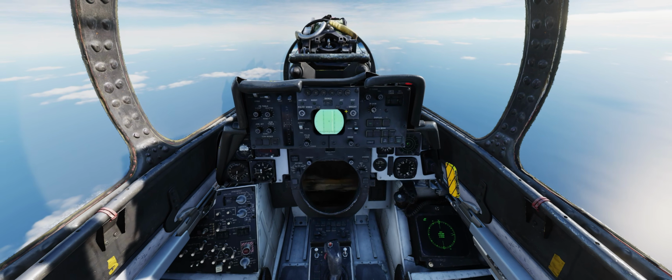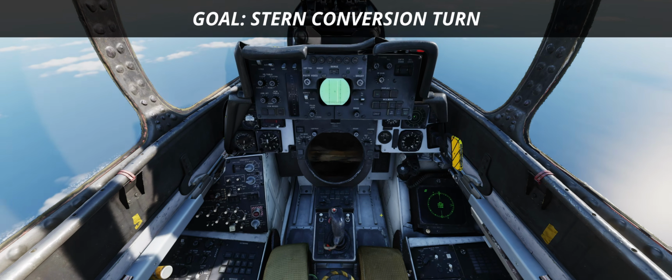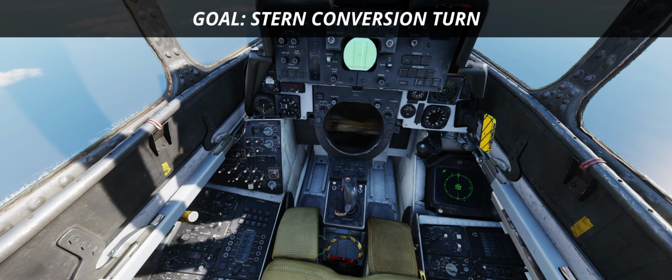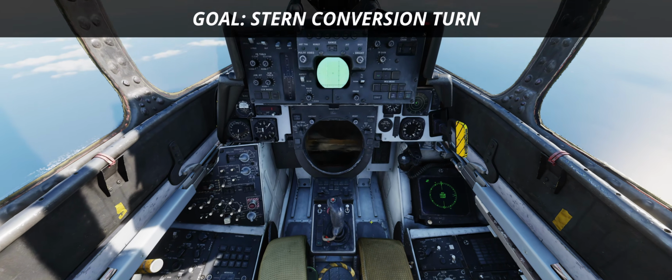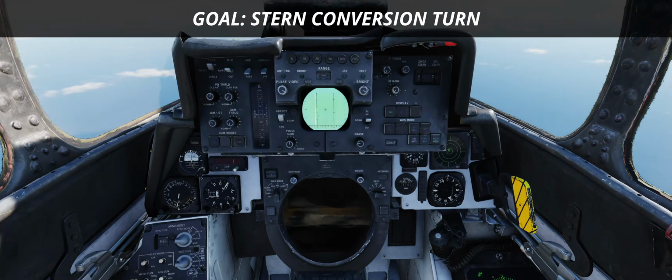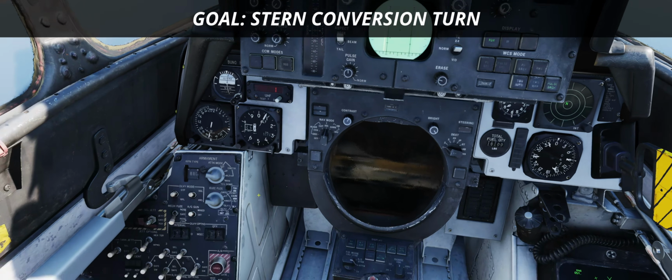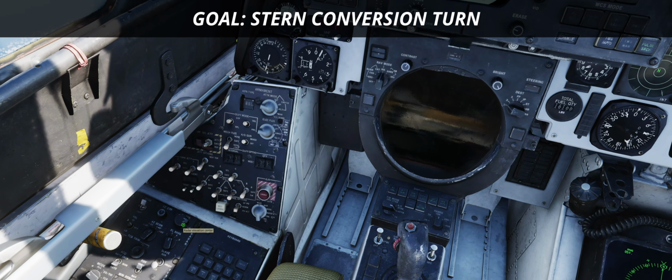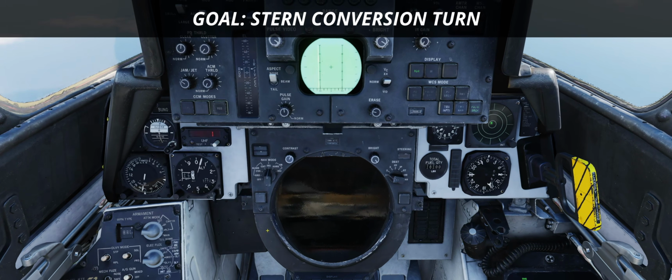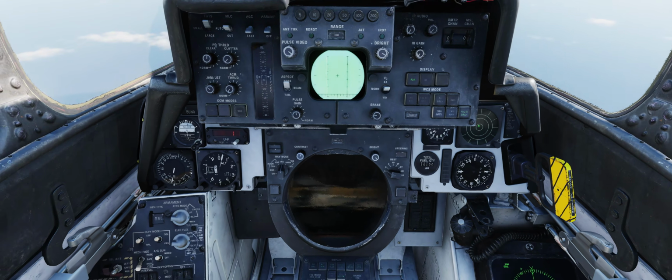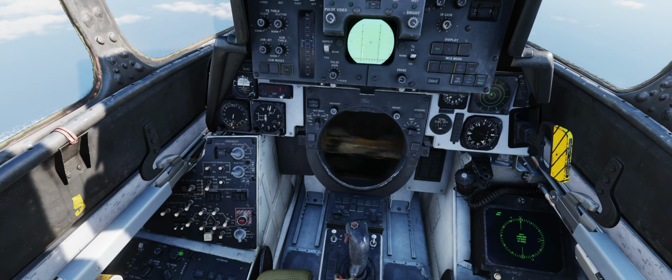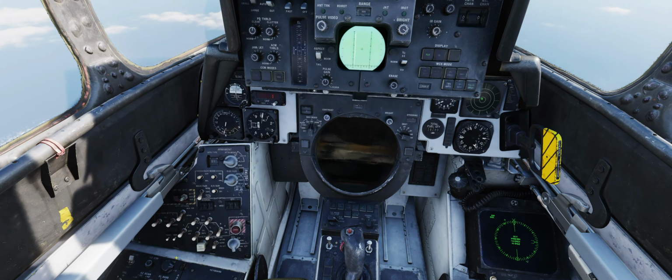Another scenario this time we want is turn conversion. From the wizard perspective, the goal is handing over the aeroplane in a known position suitable to perform the turn. In this case, I will try to do it, but I cannot guarantee the quality of the maneuver. However, most of the time, moving to pure pursuit at about 7 nautical miles works okay-ish for a wings level in the rear quarter within a couple of miles from the target.